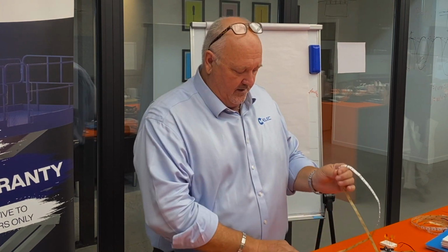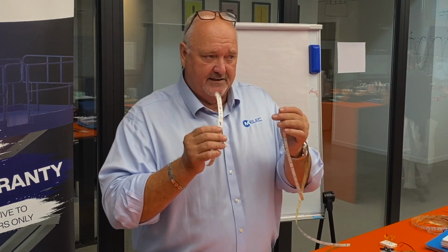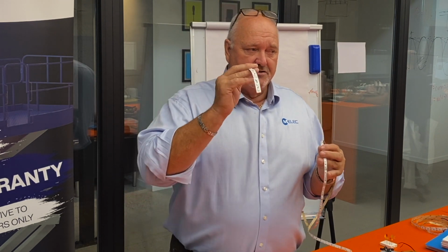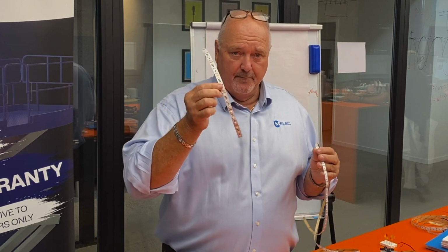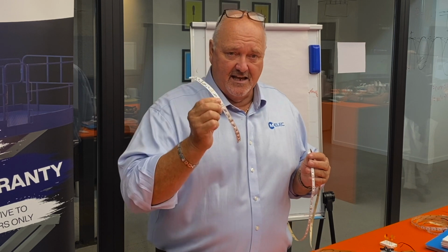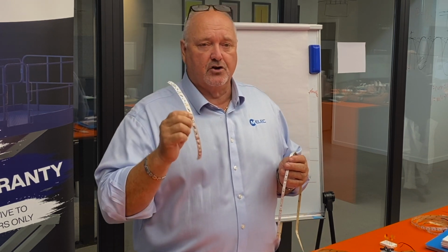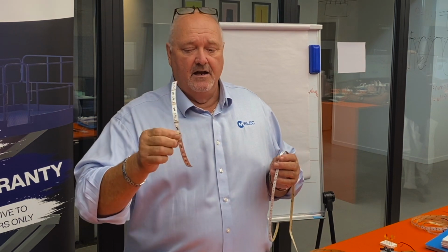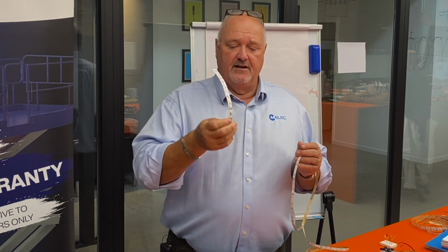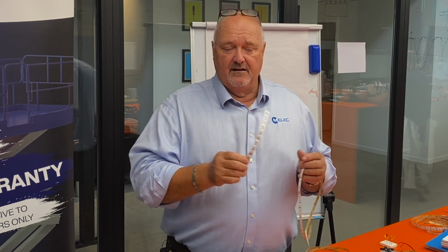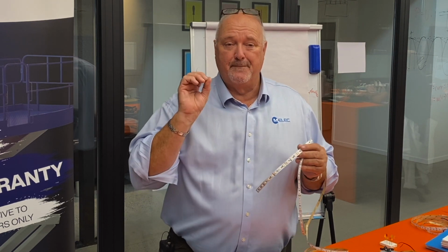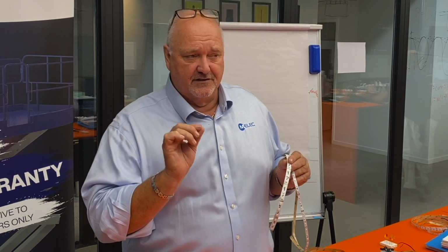Now, the circuit board and the composition and the quality: for higher power LED strips, the quality and specification of the underlying circuit board matters. Let's go back to our two samples here. The printed circuit board under this 28.8 watt per meter strip is thicker and wider to compensate for the other colors, but also for the additional heat, and the actual printed circuit board is bigger in surface area.